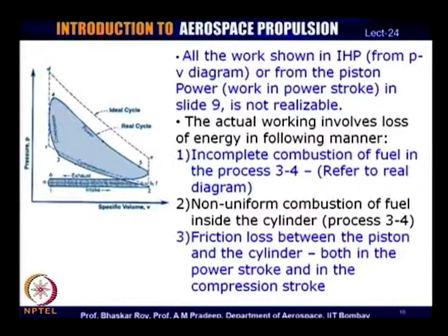Now, the cycle efficiency, as we have seen, is directly influenced by the compression ratio, the pressure ratio and the temperature ratio. The more the compression ratio or pressure ratio, we have seen the cylinder would need to be built heavier, and these things, as I have mentioned, are prohibitive. So, if you want to overcome some of the incomplete combustion by building a heavier engine, you really can't do that, because the aircraft requirements put a prohibition on such increases.